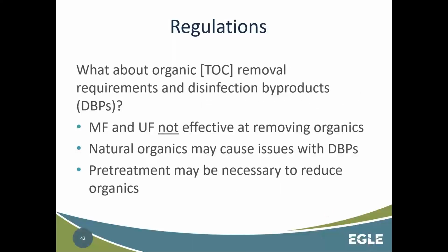All right, regulations. What about another part of surface water treatment? We tend to emphasize, rightfully so, turbidity removal because that's an acute contaminant that we're dealing with. But another big part of surface water treatment is removing and controlling your organics, because if you have excessive organics in your water and you introduce your disinfectant, then you're going to be forming disinfection byproducts, and there's that whole balancing act.